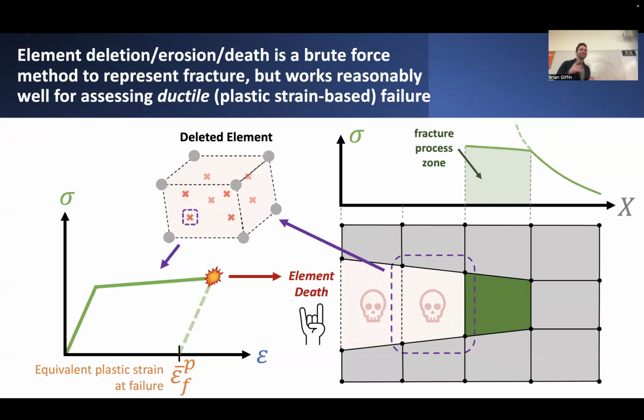Now, the last one that I'll point out has various names. Some people call it element deletion. Some call it element erosion. I'm personally partial to element death because it's kind of like the elements at a certain point, when they reach some critical value of maybe stress, but maybe something else, you just delete them. You get rid of them. Sometimes that's a bit of an approximation, but sometimes that's the only tool that you have at your disposal.